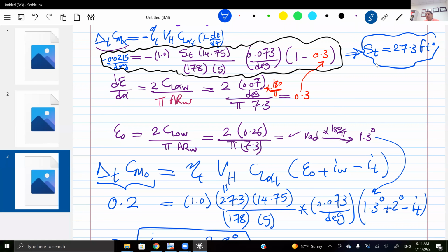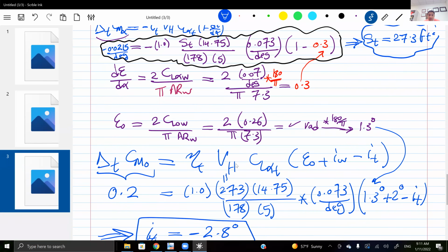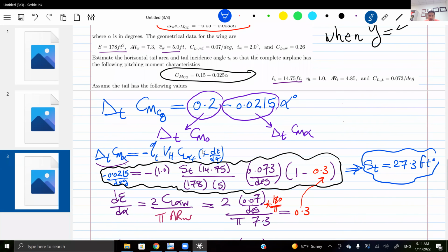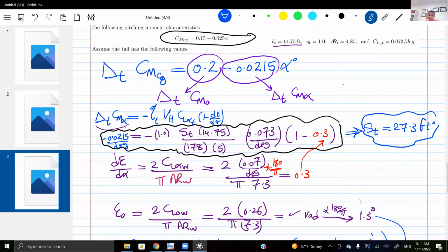It will be your responsibility to size the horizontal tail area to make sure that you get enough stability. And probably there will be more freedom here as to how you are going to sit it on the airplane, the sitting angle of it, to ensure a good balance. You can see I tail really adjusts CM naught, so it adjusts the balance. S tail really adjusts CM alpha, so it adjusts stability. Any question about that?